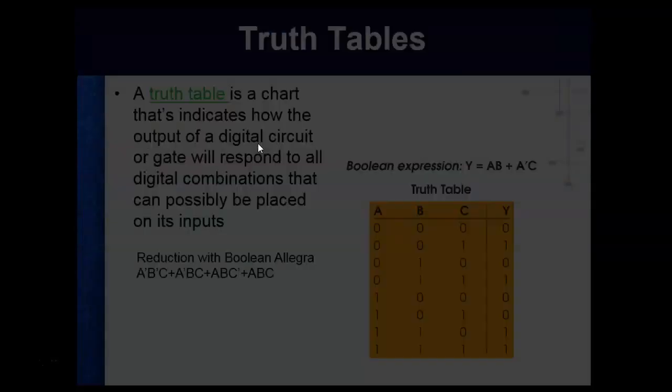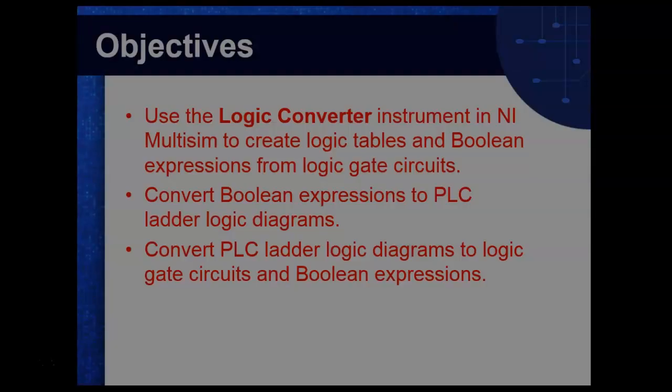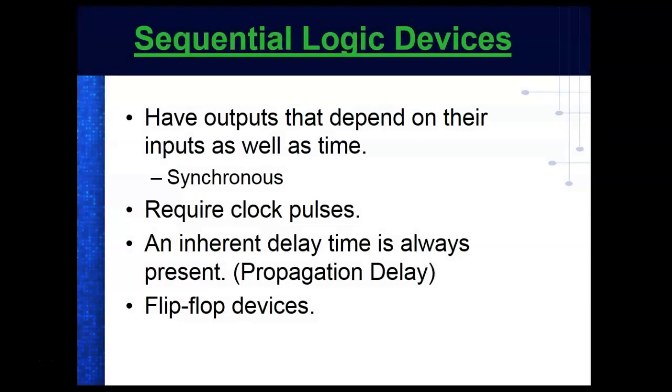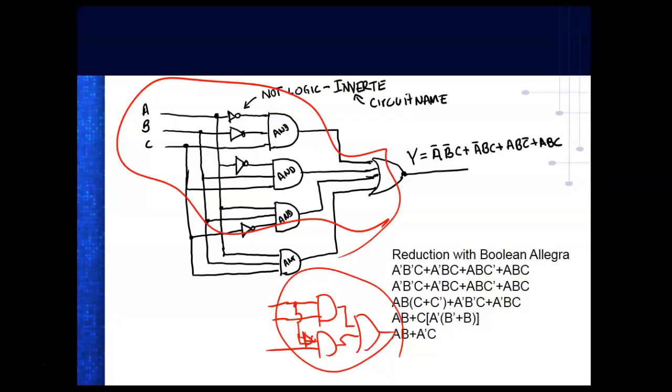All right, guys. Any questions? Y'all want to talk about the logic? Got any problems? If y'all are taking digital, y'all rip that up. What we teach in digital is the ANSI, American National Standards Institute, symbols, because that's what you'll run into in digital circuits. But in PLCs, they use the IEC symbols. But you can draw the circuit out and you can program.